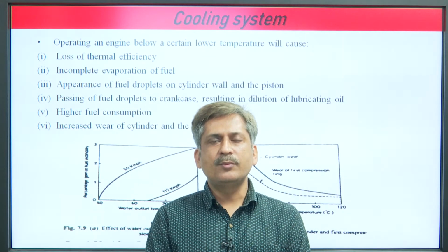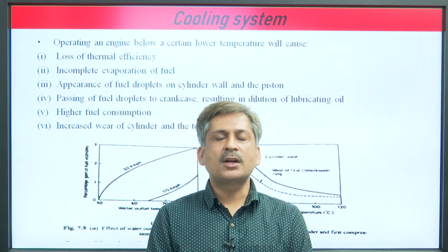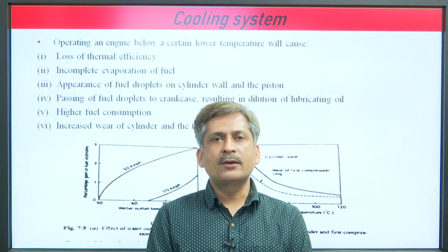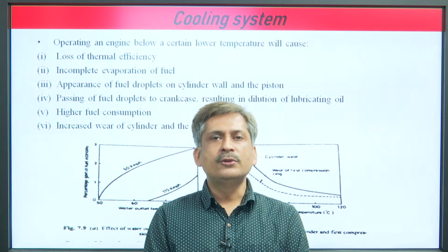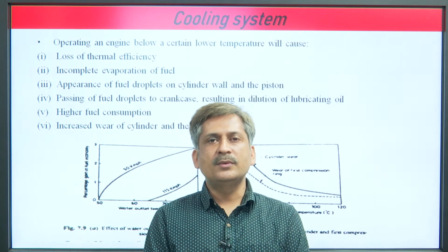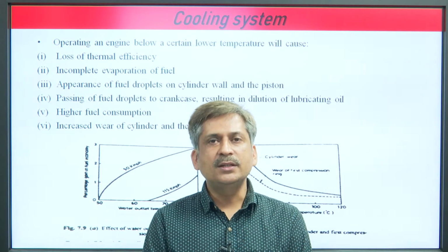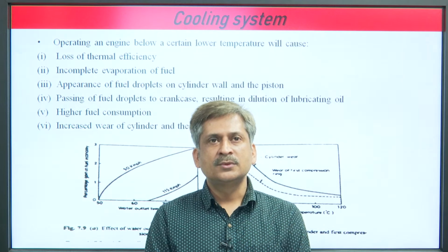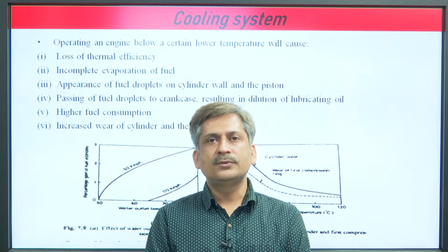If cooling is not effective, the fuel will not evaporate in the required interval of time, and if it is not evaporated, it will not mix with the air molecules. The final effect is on the mileage of the engine as well as on the emissions of the engine. So incomplete evaporation of fuel should not be there. Fuel should be evaporated in the required interval of time.